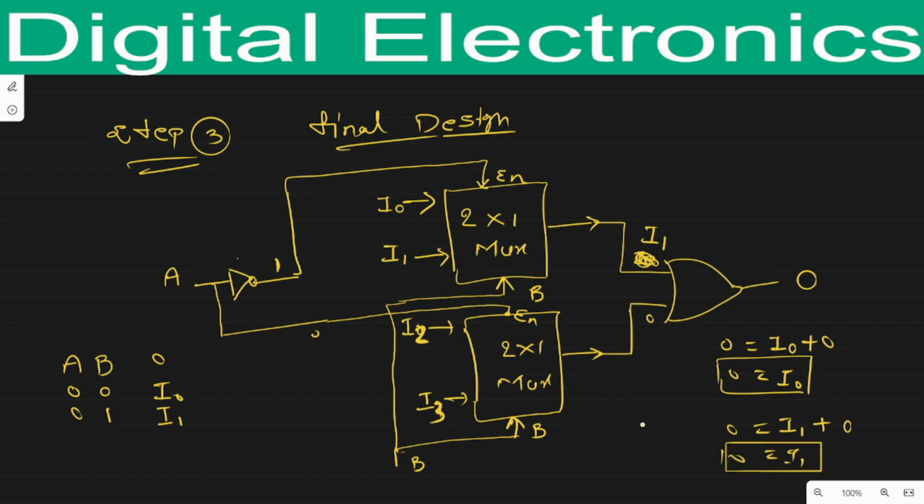Okay, now what happens in the third case? When A equals 1 and B equals 0, because of this NOT gate, this will be 0 and the lower one will be 1. So when this one is 0, it deactivates the upper multiplexer, but it activates the lower multiplexer.